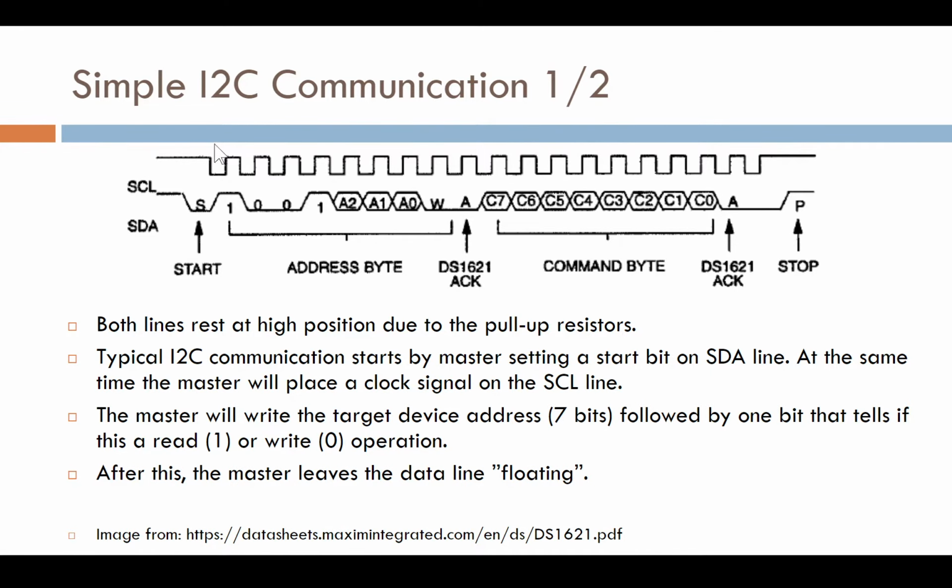And the start condition is actually when the clock is still high and the data goes low. So data goes low first and clock is high. That means now we start sending. Immediately after that,